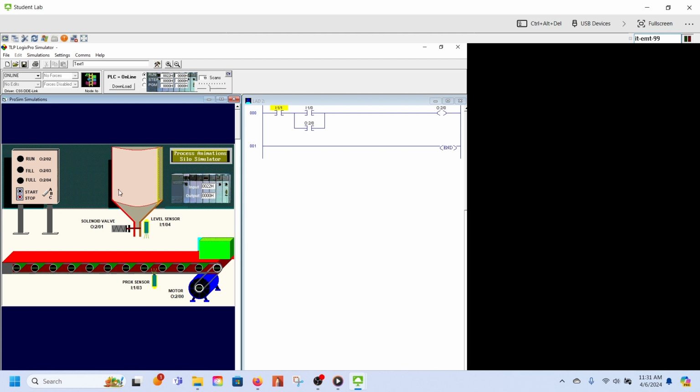So now we are wanting this, when it is A, to run like that. So here is how we're going to modify our program to do that. So we're going to set it back into program mode. We're going to go back to our instructions. First, I'm going to go ahead and put in a branch. And the branch isn't going to go where I need it to, but we'll make it work. So we're going to click on our stop button here. We'll move it inside our branch. Same thing here.